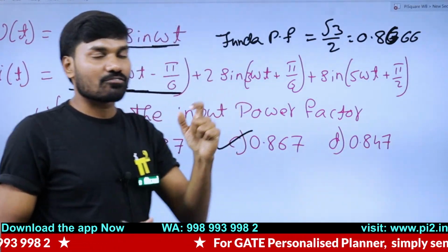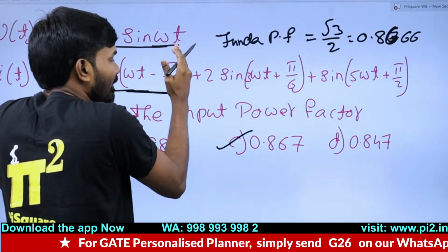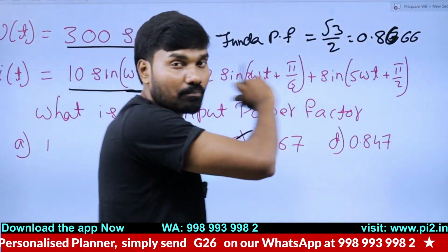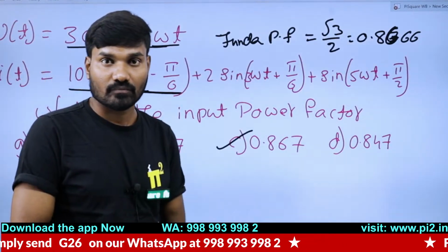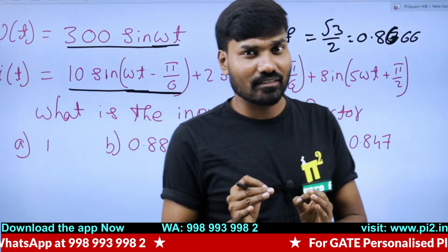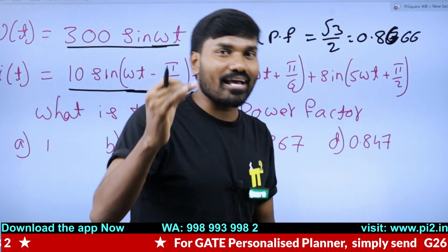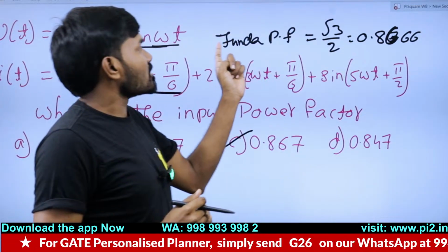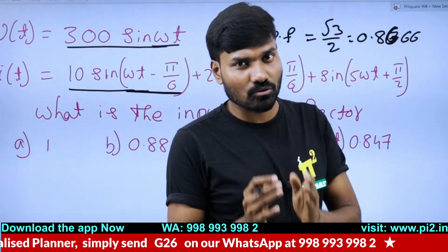But in the question, it is asked not just about the input fundamental components, but for the entire input current, considering the complete input current for the power factor. In that case, I gave a simple tip: the input power factor is always less than the fundamental power factor. That is the tip I have given in the course.